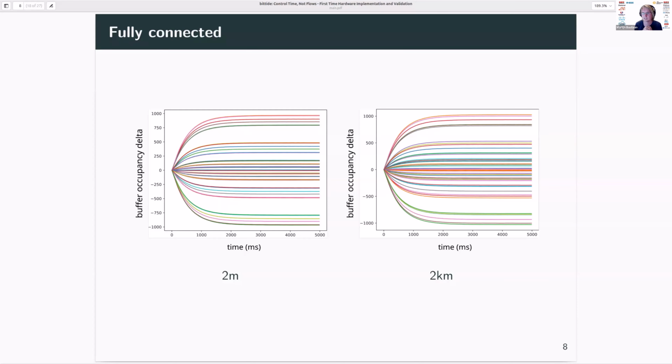Measurements show that this increases the total latency, as you would expect, by about an order of magnitude. But as far as we can see in our experiments, the clock control is just insensitive to this. They're not shown in the paper. We've also done this experiment for long-running tests. We've been running tests over the weekend, and still in those situations, the buffers do not get more than 2 from their midpoints. So that is to say, these systems, when clock control is active, are super stable.